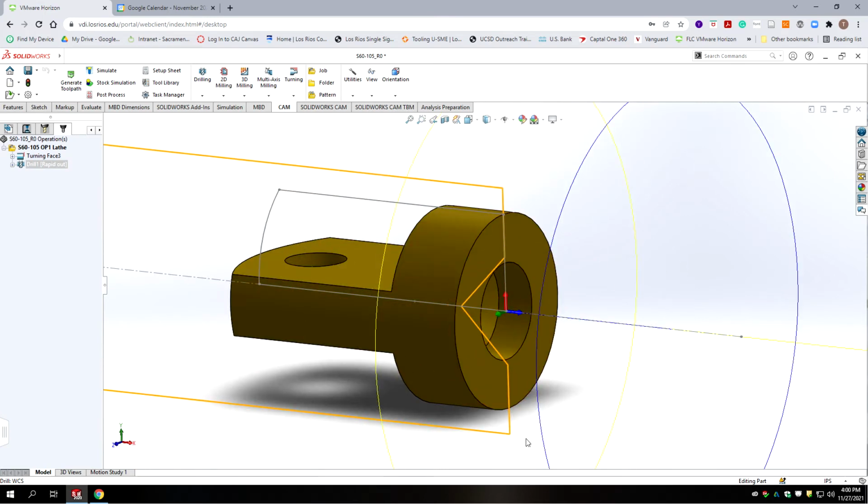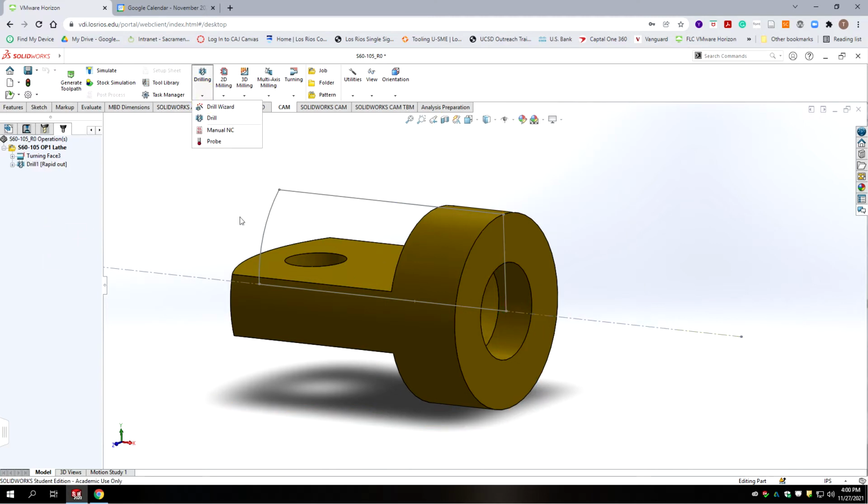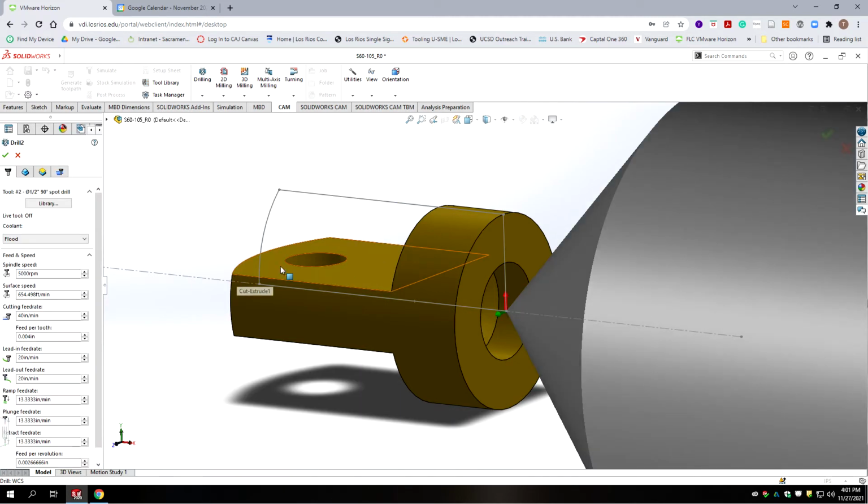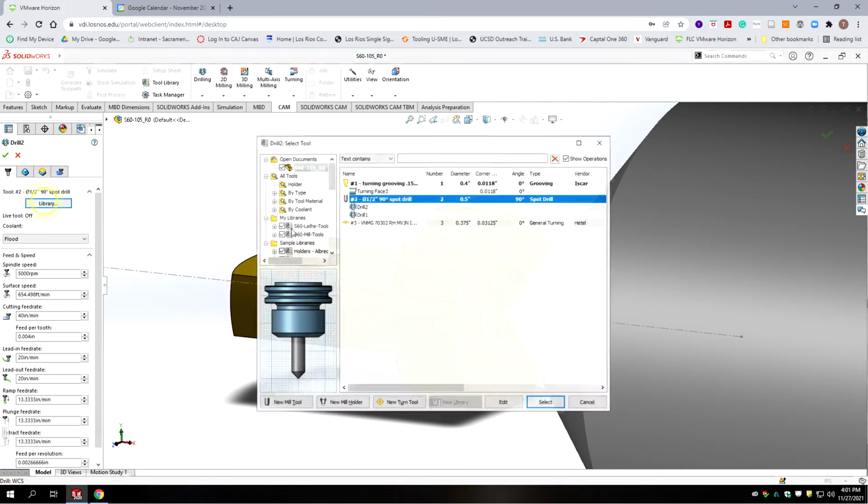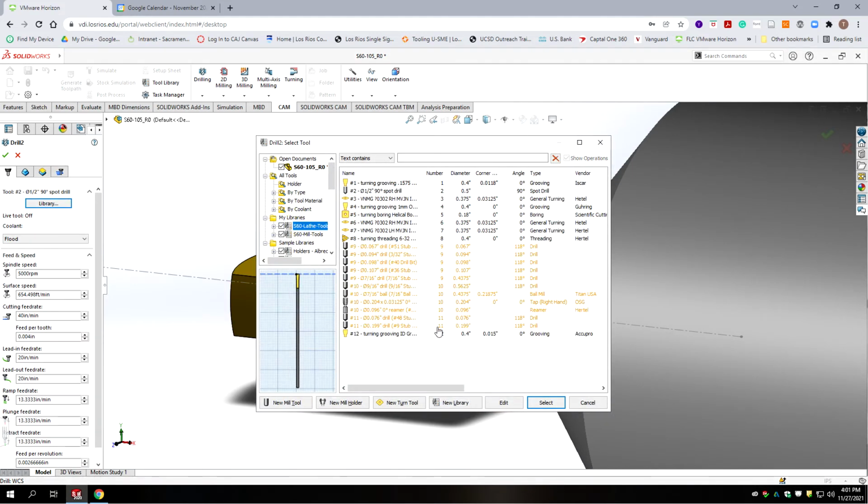Now this hole is for a part to be soldered in. If we look at the next level of the process, we're going to go towards the higher end of the tolerance on it. It's just going to get filled with solder. It doesn't need a specific press fit. So we need to select our drill from our list, and go to our library, lathe tools, and we should be using the 98 thousandths drill or number 40 drill.